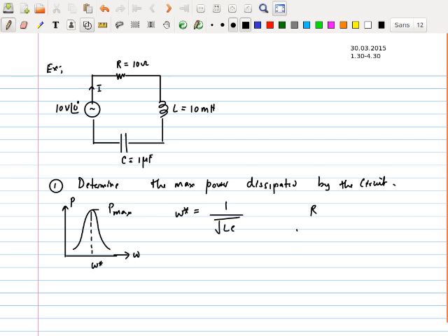And we do realize that happens at resonance, and at resonance the entire circuit is going to be resistive, so the total signal power that is going to be dissipated is going to be I squared R, or you could also have written it as V squared over R, because we already know V. The voltage drops across the inductor and the capacitor go in opposite directions. These two will actually cancel each other out, so the entire voltage drop is going to appear across the resistance, right?